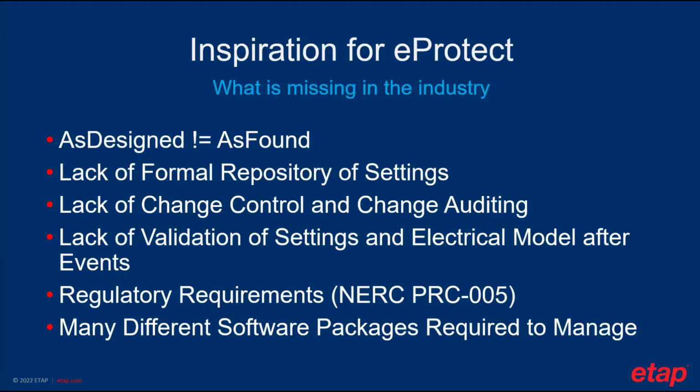So what was missing in the industry that we felt needed to be resolved? First, the as designed oftentimes did not match the as found. Someone would go in the field and change the settings on the relays for potentially good reason, but that never makes its way back to the engineer who is doing the protection coordination studies. This can lead to major issues if you build new protection schemes assuming that what you have already is accurate in your model.